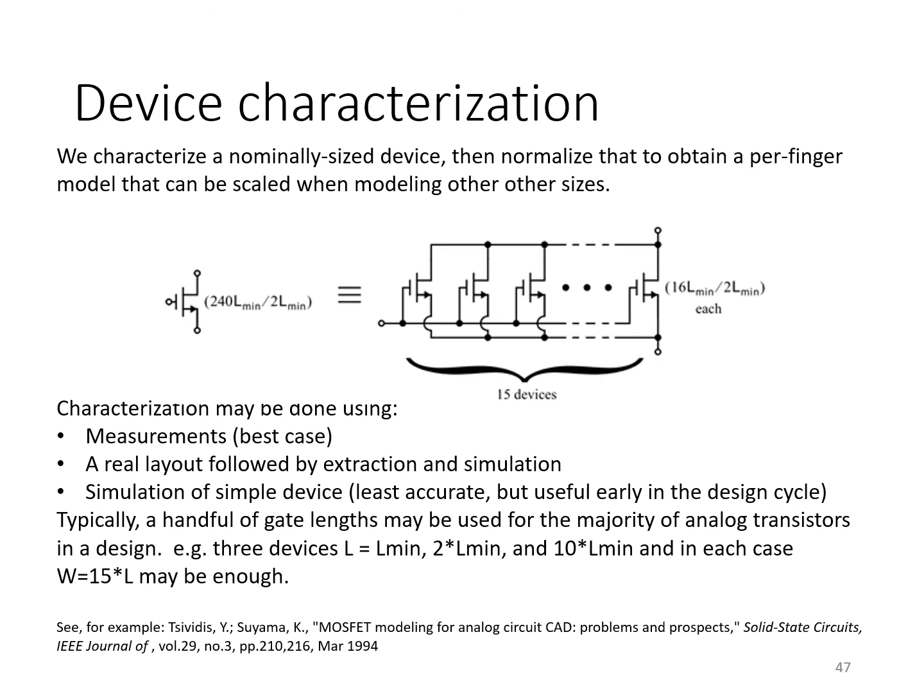So, again, you want to characterize a few different gate lengths here. Here I'm suggesting maybe the minimum gate length, 2 times the minimum gate length, 10 times the minimum gate length, and you have 3 sets of model parameters that you can apply to the rest of your design.